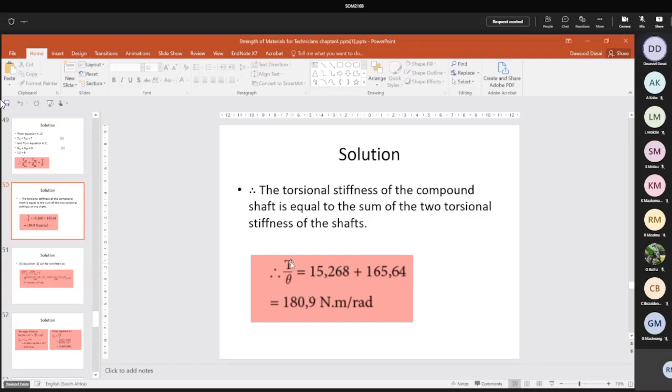The formula gives you the unit. You can see you got torque, which is Newton meter, upon theta, which is angle of twist in radian. So what's the problem? This slash means divide. If you got moment, it's force times radius, Newton times meter. So the units are Newton meter, not Newton stroke meter. That stroke means divide. Some students lose two, three marks unnecessarily. You're sitting at 37 in the exam. Fail sub minimum because of three marks because you lose on units. Units are important, students.